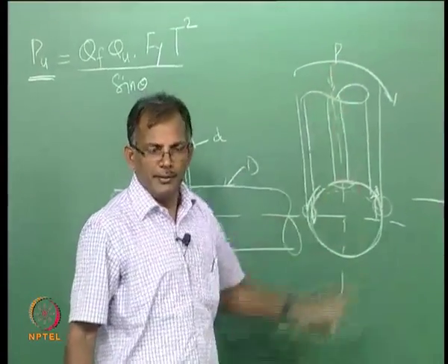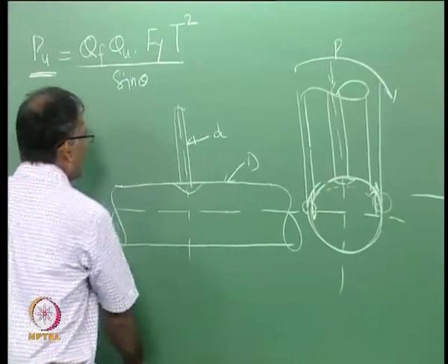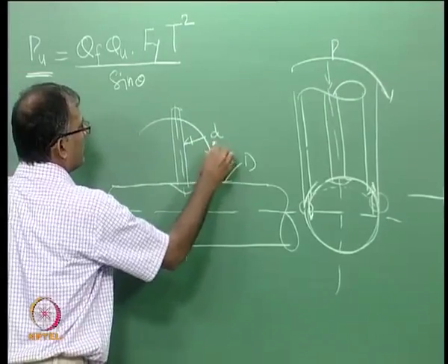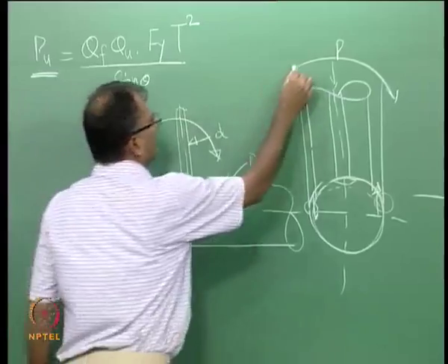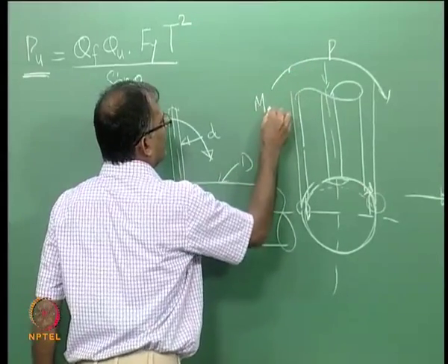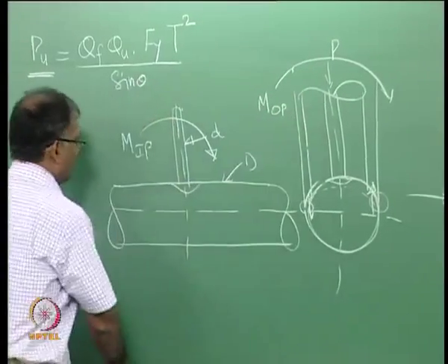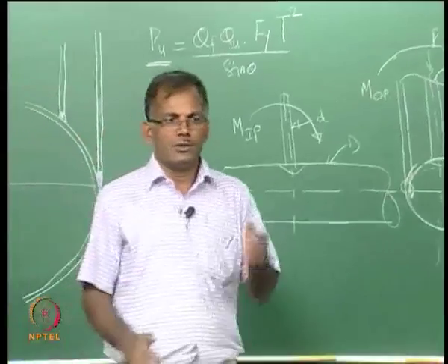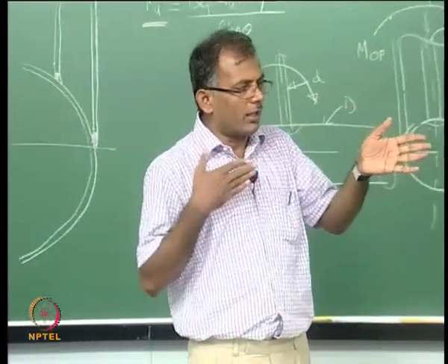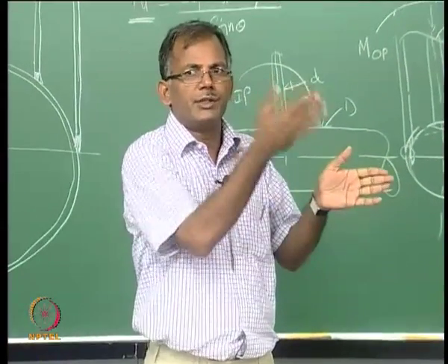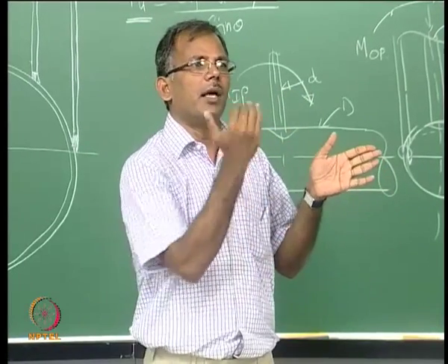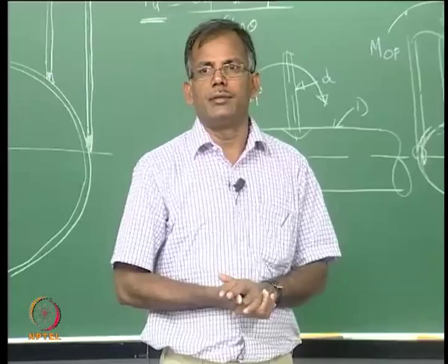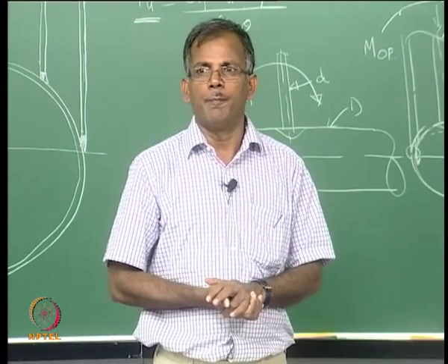If the brace is like this, this is moment in plane, this is moment out of plane. So whenever you look at the joint, with the chord running along and the braces seen, that is in plane, the moment is in plane, and the one perpendicular to the chord is called out of plane.